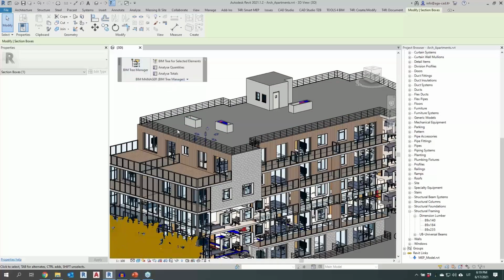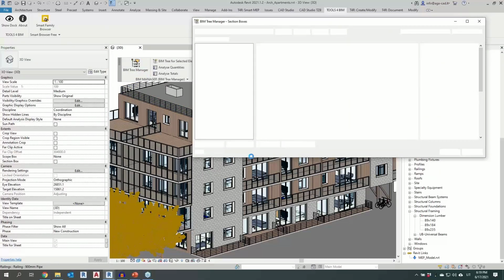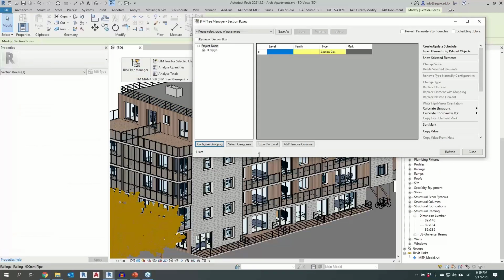Later, we can go and look a little bit more into the architectural side of the project. We already did columns, walls, so right now let's do windows, doors, and furniture and see how we can push information from the room into those elements. So later in the schedule, we would know how many windows each room has, how many doors, and so on.